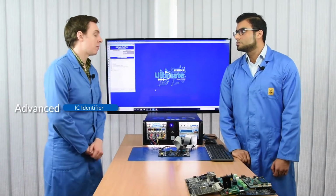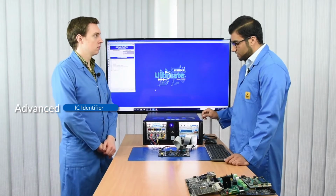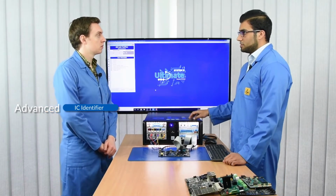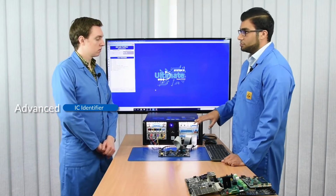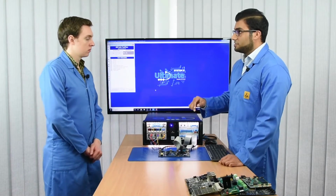So Mini, what can you tell me about the Advanced IC Identifier? Sure. The Advanced IC Identifier is one of the many instruments that come with the BoardMaster, and this specific instrument is used with the ATM, the Advanced Test Module. What this instrument allows you to do is find ICs that work in the same way as the IC you have in front of you. This test looks at the functionality of the device, making sure that it's the same as the one we have in front of us.